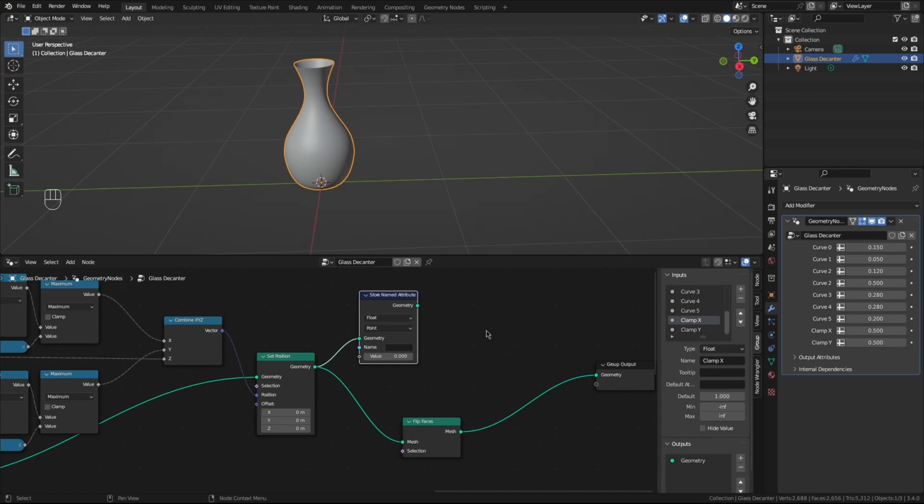Also, when I do the scaling up of the interior to the exterior, the bottom of the decanter will move down a little bit, the sides will move out, and the top will move up. That's just the way scaling works. But I want the top to be flat. So if I mark those places, I can push them back to flat to have the interior match the exterior, and that way the lip will be horizontal.